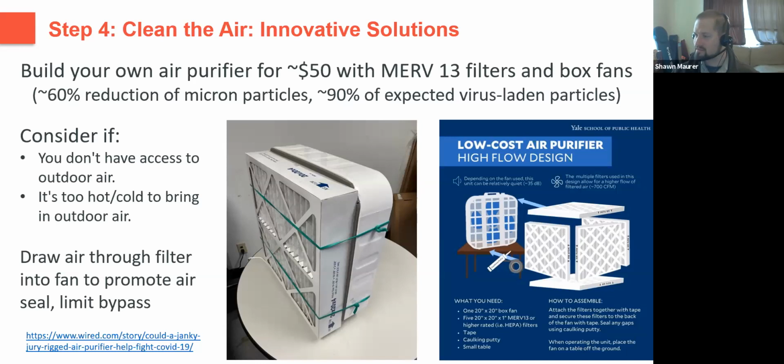If your air handling systems cannot handle the upgrade to a MERV 13 filter and you had to drop back to a MERV 8 filter, or you've just got a space that needs some additional air filtration because there's a high density of occupants, there's a simple, innovative solution that a lot of facilities have come up with to have an air purifier in the space for less than $50. Whereas if you go with a professional air cleaning device, those tend to be in the $250 to $350 range.